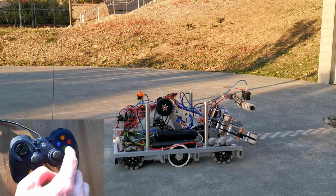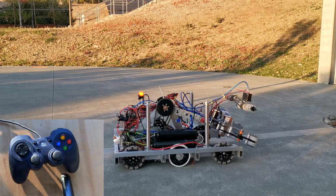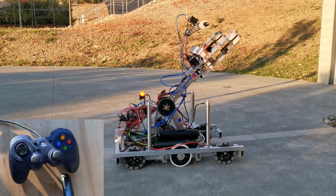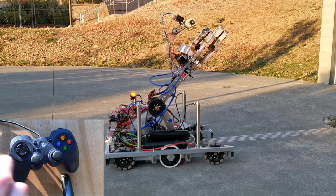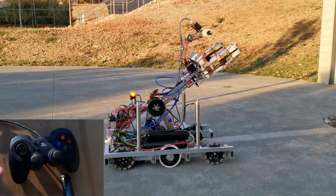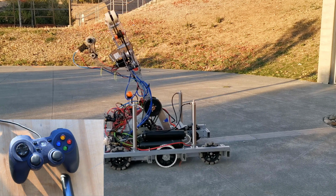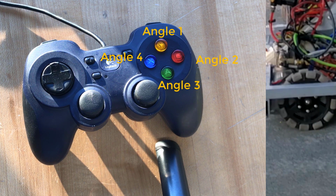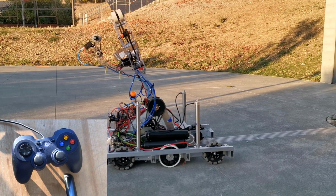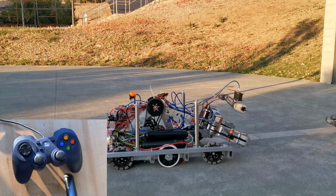Although the arm can be hard to manually control using joysticks, we can try to automate it in the code to let the program control the arm for us. This way, instead of constantly tweaking the joystick, we can simply press a button and program the robot to tweak the joysticks for us. For example, if we only need the arm to rotate to 4 fixed angles during a match, we could control the arm using 4 buttons. Every button would tell the arm to go to a different angle. And when we want the arm to move somewhere, we just need to press the corresponding button.